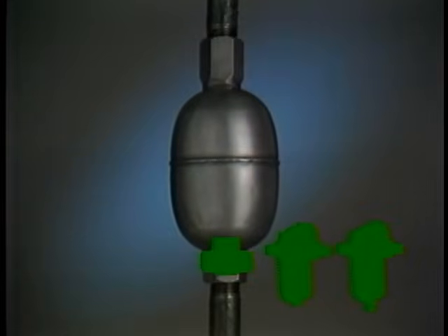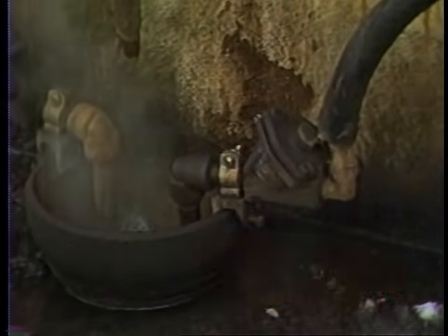The IB, DC, and disc can withstand some freezing without trouble, with the addition that the stainless steel IBs can actually expand under severe conditions and still operate after they are thawed. The more delicate bellows elements and the float in the F&T can be crushed if they retain condensate in their bodies when temperatures drop below freezing.